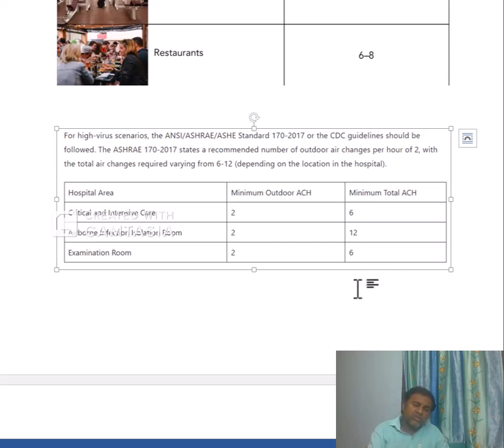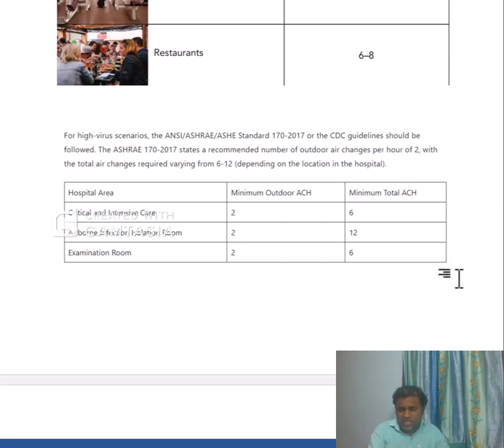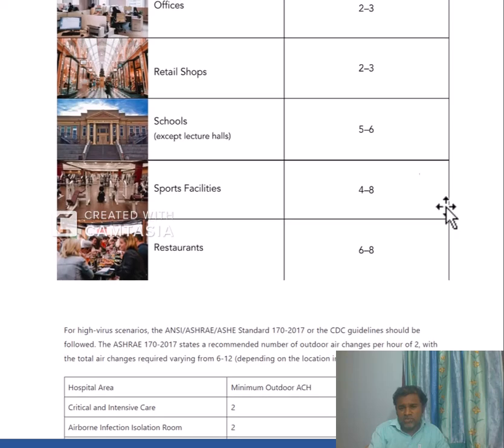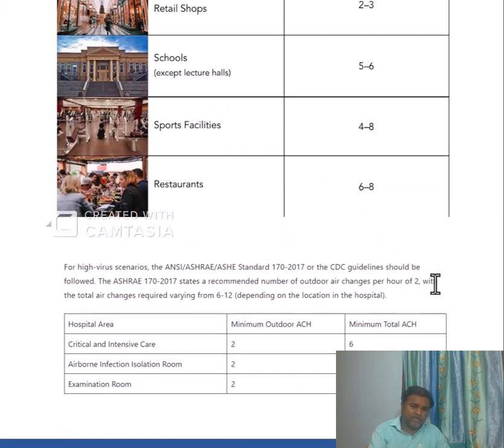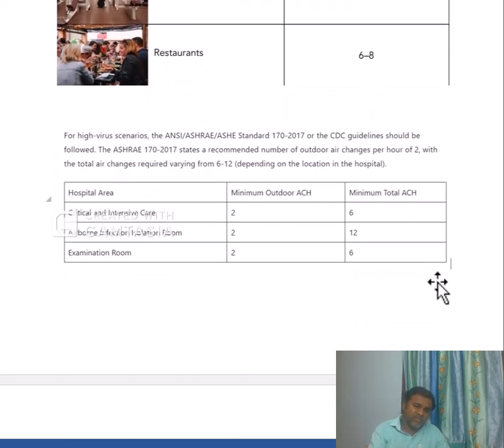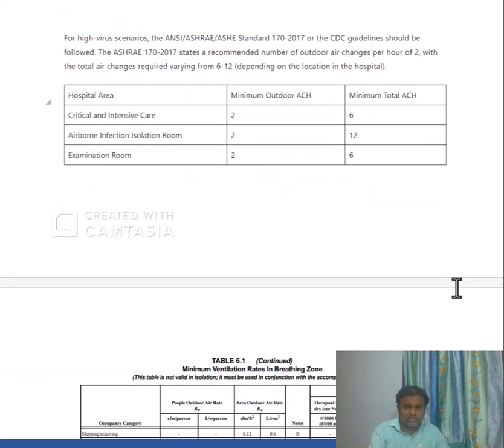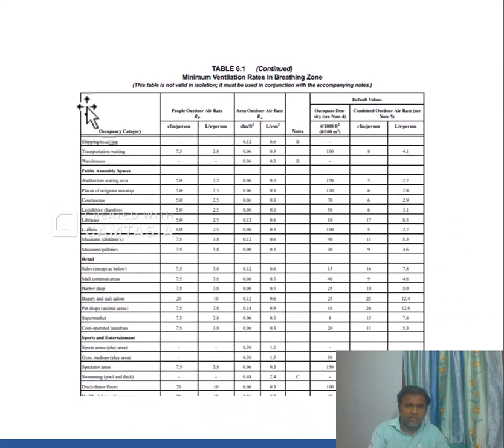Guys, try to understand and memorize these air changes per hour values when you are designing for a particular process area, maybe the healthcare sector or a normal factory, or banks or financial institutions, or educational institutions also. You need to go through these particular tables and take reference of these values. These values are all based on ASHRAE. See here, one more thing here.